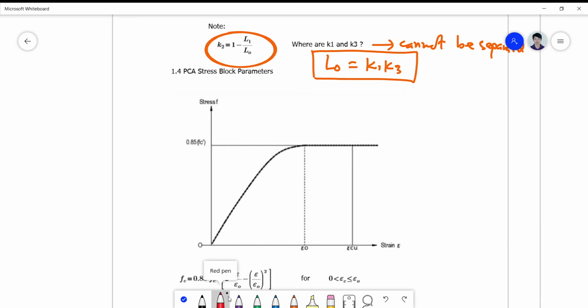is giving us in terms of the stress strain property of your concrete. Okay, so we have here, this graph is almost not linear but almost linear at this point, up to about 0.5 or 0.6 maybe, and then the abrupt change in curvature at around 0.8. Okay, and then at its peak, it is assumed to continue its strain increase without change in the stress. Okay, so this is actually horizontal.